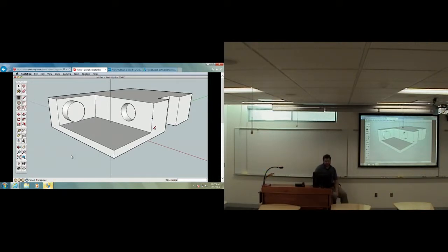All she's doing is she selected the rectangle tool over here on the left, and then she brought that pencil that shows up, and she just ran it over to the edge. She's not clicking anything. And as it sits on the edge, it says, okay, you're on the edge, gives you that little red dot, and if you're sitting on the corner, it shows you an end dot, and then as you get towards a midpoint between 2 points, that's this point here and this point here, then it shows you the midpoint dot, which is kind of like a neon bluish, turquoise-ish color, okay?